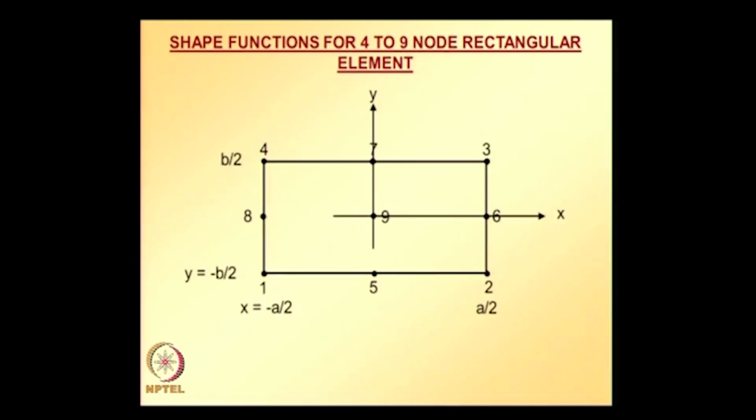And so this is the element that we are considering. All the nodes are numbered and the corresponding locations can be easily figured out from the figure that is given. And here the way the nodes are numbered is very important, because with this particular node numbering scheme, shape functions for higher order elements can be constructed by adding terms into the shape function for lower order elements.